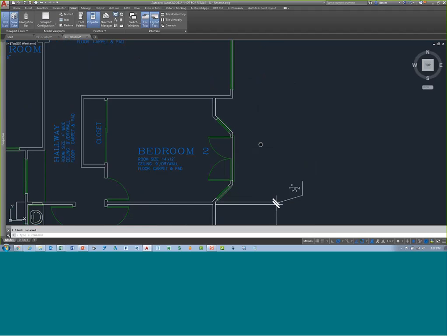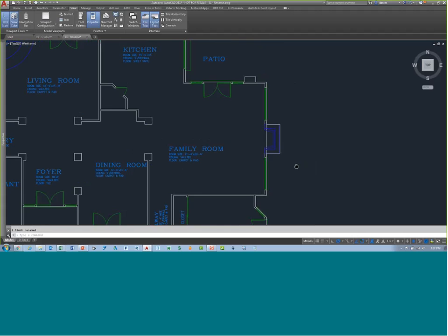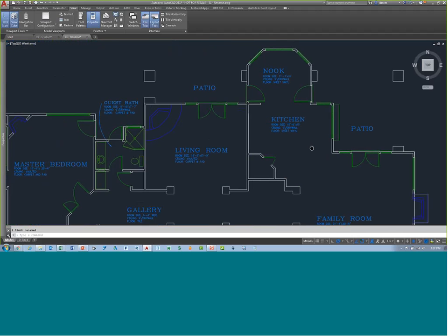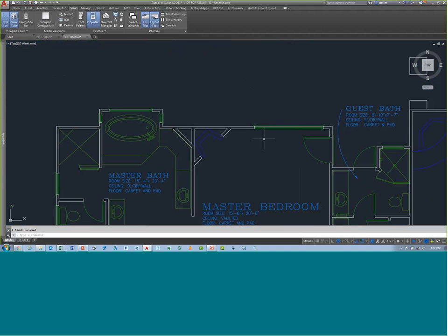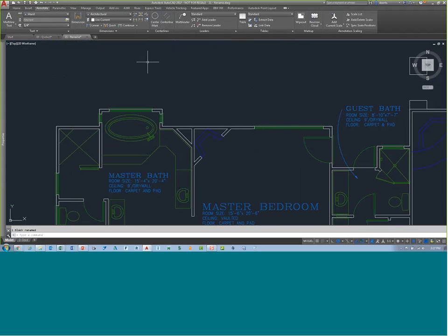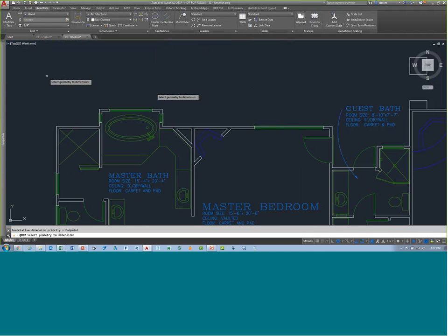Maybe you have to dimension some stuff and you really don't have time to be methodical about dimensioning things. You just want to do a quick dimension. That's another tooltip, number 22. And that QDim command is actually an old command. I think it was as far back as release 14. So you can just type in QDim or click this icon right here under the Annotate tab. And depending on the visual style or the annotation style that you're working with, you can set it.